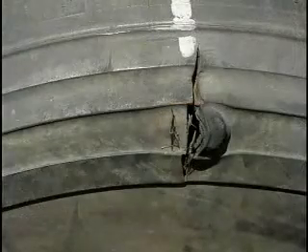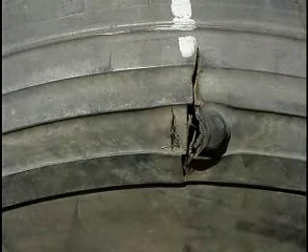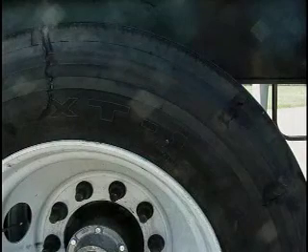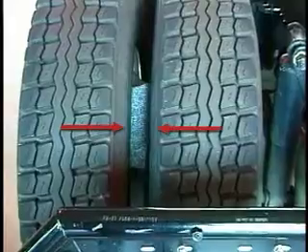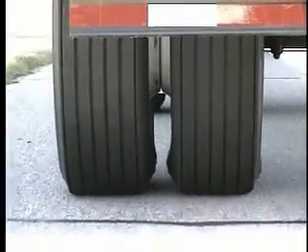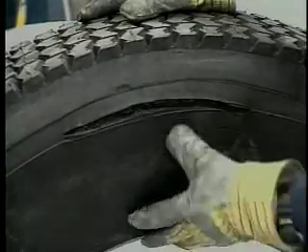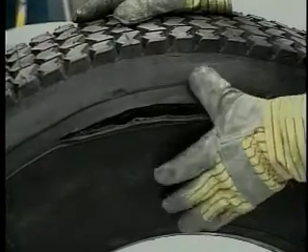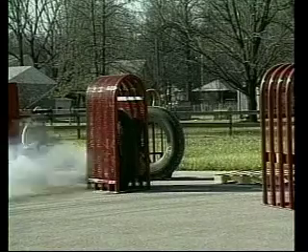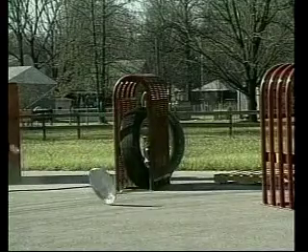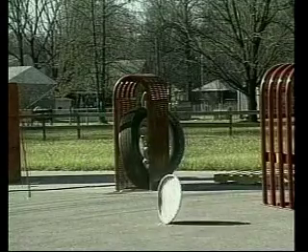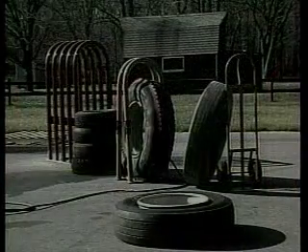The most significant causes of this condition are damaged cords, resulting from the following: cuts in the crown or sidewall area, allowing moisture to reach the steel cables, bead damage, improper repairs, objects wedged between duals, and dual wheel run flat. This zipper rupture is a premature fatigue condition in a casing. What makes this condition serious is that it is generally created after the tire has been removed, improperly inspected, repaired, and re-aired up.